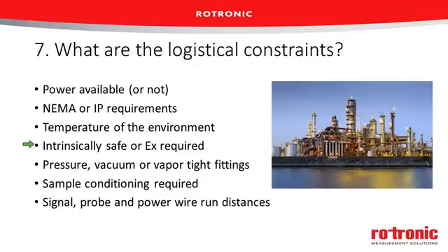And if we're in one of these environments, we also have to understand that the regulations for this are not harmonized globally. Different regions have different requirements, and just because an instrument has been rated to be intrinsically safe in one region, it might not necessarily have that same rating in a different one. So we've got to be careful of that and look out to see, does this instrument actually meet the needs for our location?